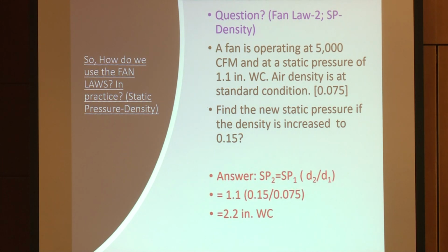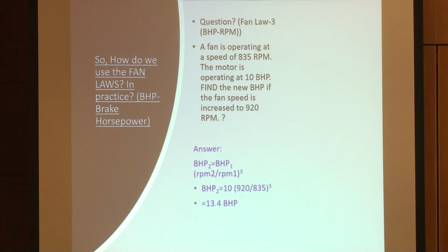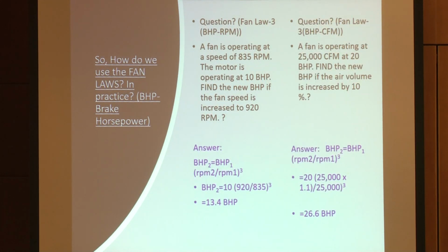Similarly, we're going to use it for static pressure and density. Again, the fan operates at a flow with a static pressure and an air density. Want to find the new static pressure if the density increases. Again, you use the formula. I told you I would go through these and show you how much and how often we use these all the time. Here we go with brake horsepower, which is going to be a cube.